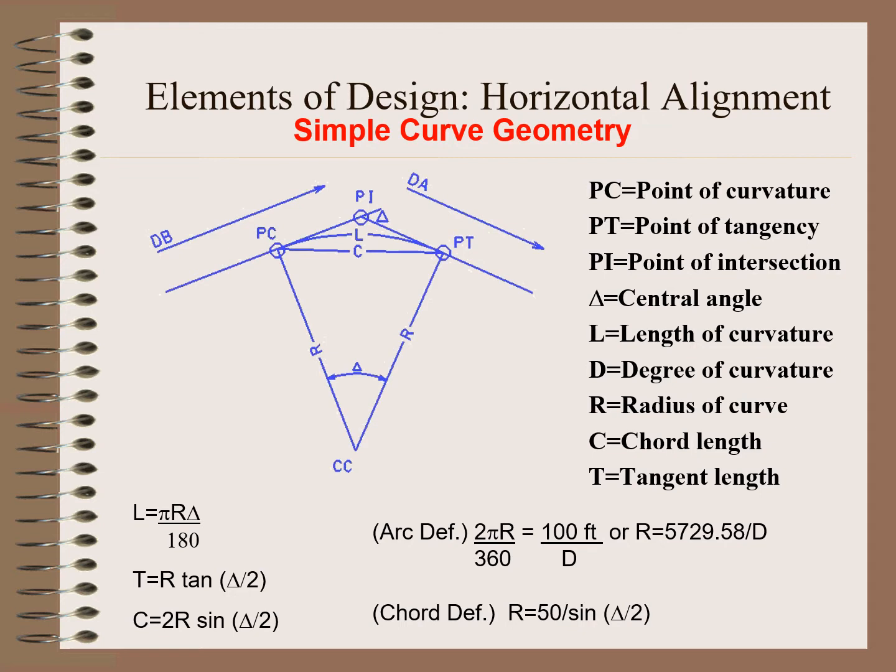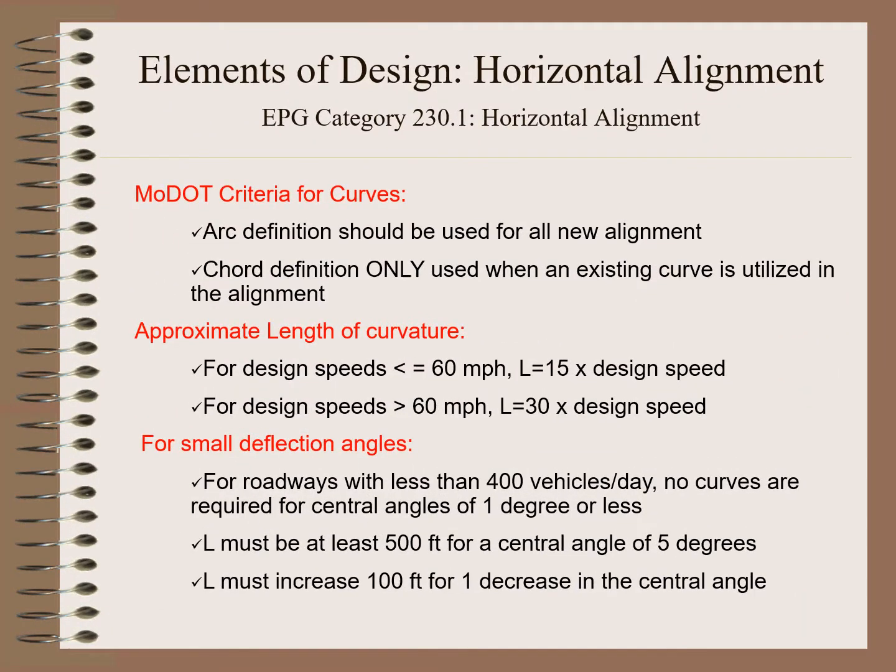Note that specifically you will find chord definition formulas and arc definition formulas. You may assume that a curve has been designed using arc definition if you don't see any notes. Anything designed as a chord definition should have in parentheses "chord defined," since it is not the norm. MoDOT criteria for curves: arc definition should be used for all new alignment. Chord definition is only used when an existing curve is utilized in the alignment and you're not changing any of the alignment.